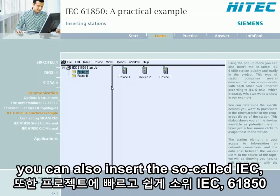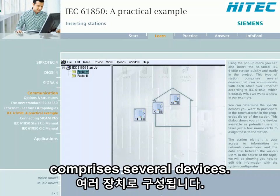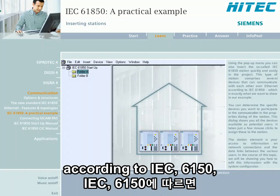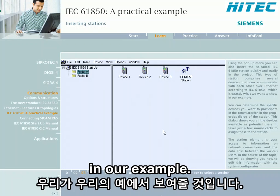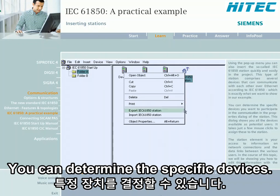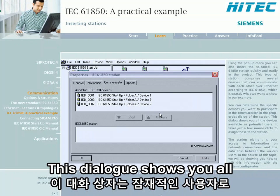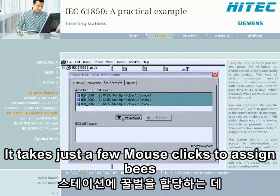Using the pop-up menu, you can also insert the so-called IEC 61850 station quickly and easily in the project. This type of station comprises several devices that can communicate with each other over Ethernet according to IEC 61850, which is exactly what we want to show in our example. You can determine the specific devices you want to participate in the communication in the Properties dialog of the station. This dialog shows you all the devices available as potential users. It takes just a few mouse clicks to assign these to the station.